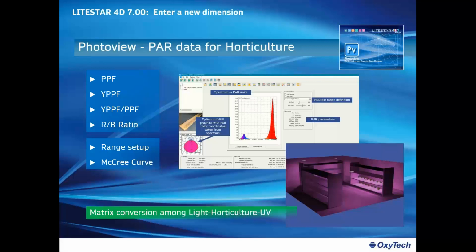diagrams and graphics. But also, another big change was the introduction of the same concept for the lighting calculation. It means that right now we don't have to add any other information. In the same way you drag and drop an IES file into your lighting design program, you drag and drop now, for example, an OXL file or an IES XML file or a UNI, the Italian file, brand new file format, UNI XML file, and the calculation will be done spectrally.